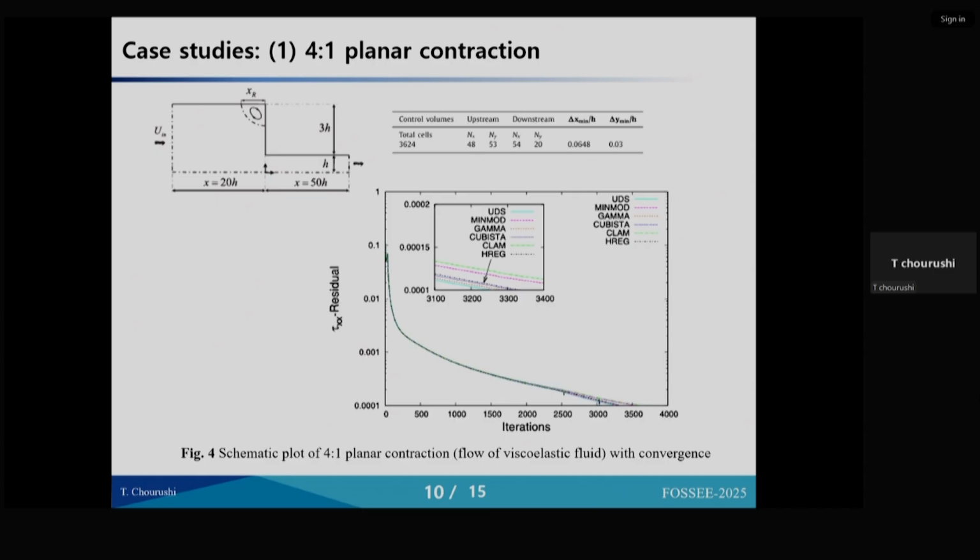If I use a lower order scheme and try to replicate the results of experiments, then whatever mesh refinement I do, my lower order schemes will not be able to match the experimental result. That is where people fail. They need a high resolution scheme, and many people use such numerical schemes so that their results come closer to the experiments.